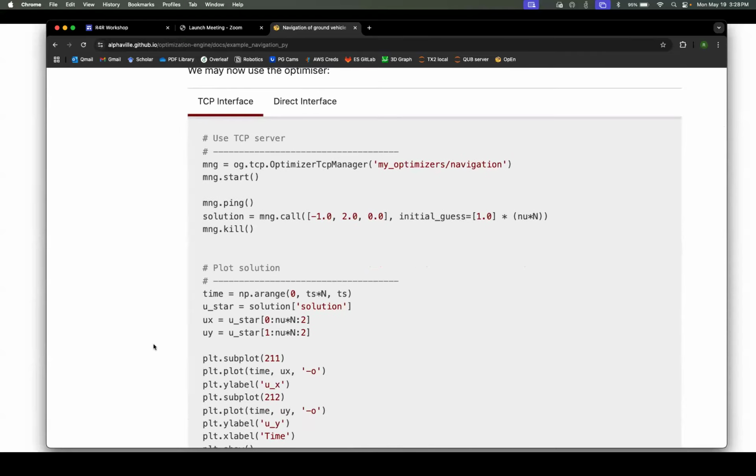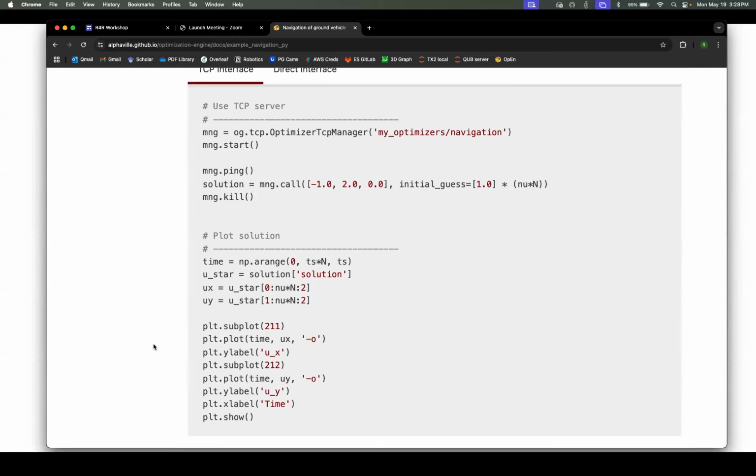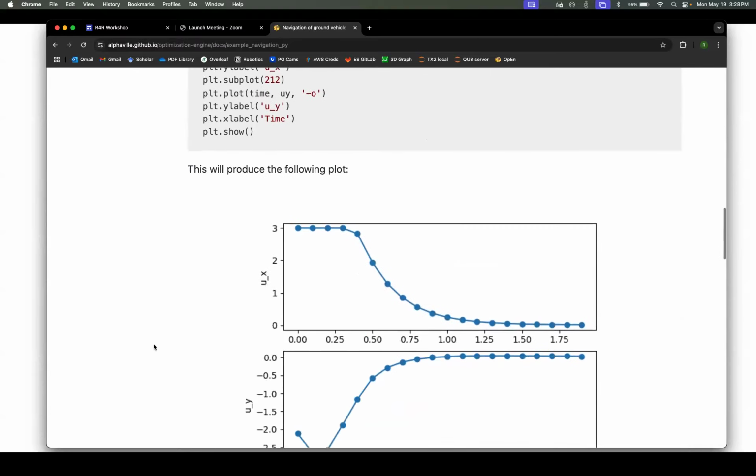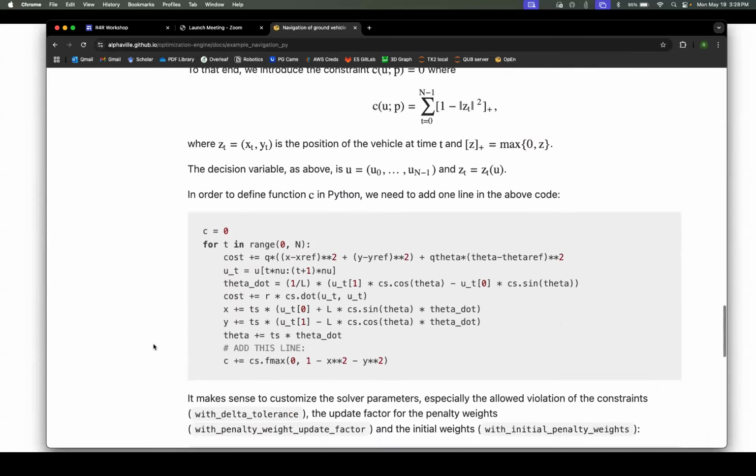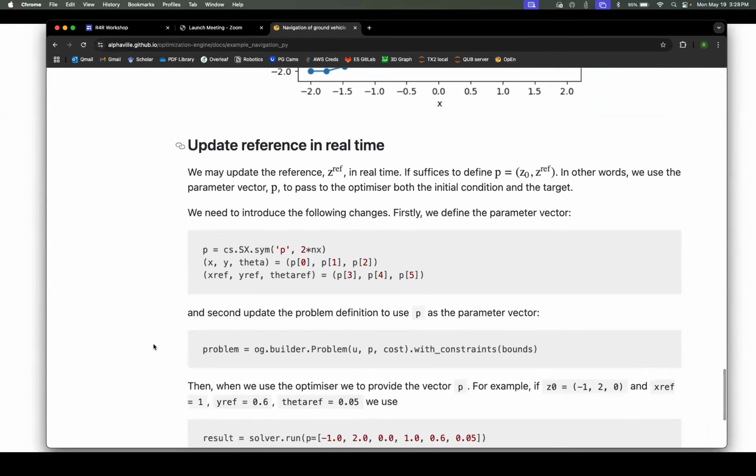But the nice thing about it, which not all optimizers can do, by the way, is that it is a parametric optimizer, which means when you're doing model predictive control and you get to this point, because you are providing the target point as a reference and a parameter, it means that while it's moving, you can also adjust your targets. You don't have to build a new optimizer for every time you want to change where you're going. So you can change your reference target, but also use your previous answer and move it around slightly, where you remove the control action you've just used, bin it and repeat the last one, and then provide that to the solver, and it takes that as an initial guess. And since it's a pretty close answer, your next solve time will be orders of magnitude faster.